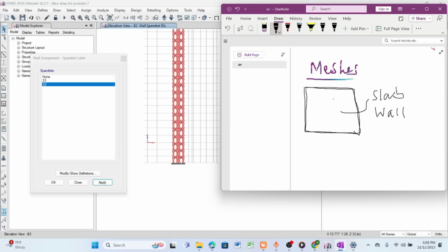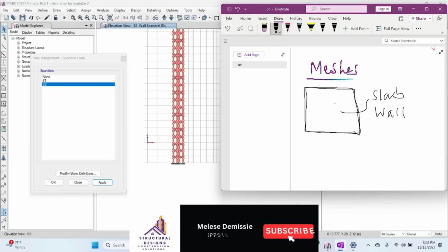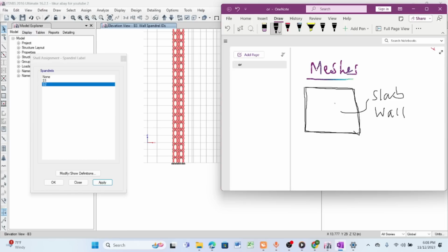internal forces of the members, because here an infinite number of points will lead to an infinite number of equations. So an infinite number of equations will not be able to be analyzed by ETABS. So ETABS will analyze a definite number of equations and a finite number of elements.